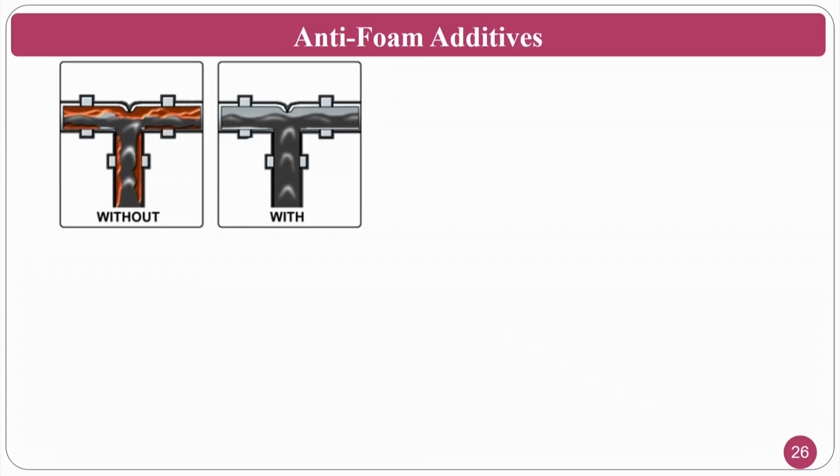With this foam you lose the visibility first, and at the same time some of the bubbles may break, which may cause some intermittent chemical actions and other things. That is why you don't want this foam in the machining conditions or as a part of the cutting fluids.